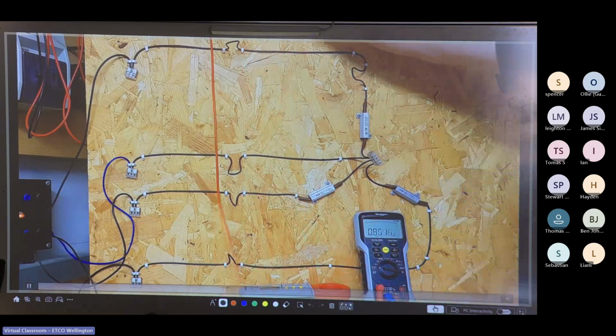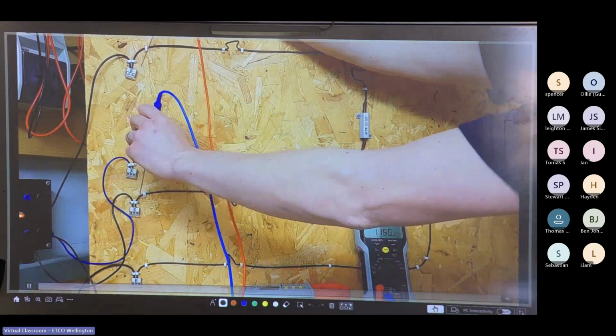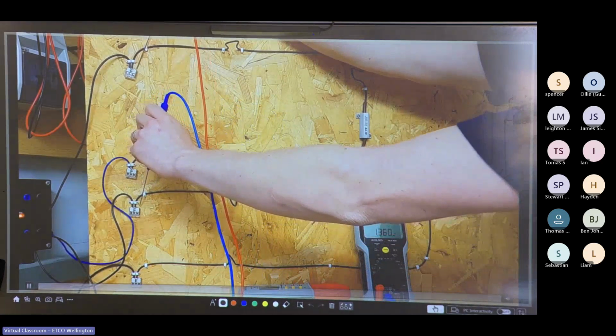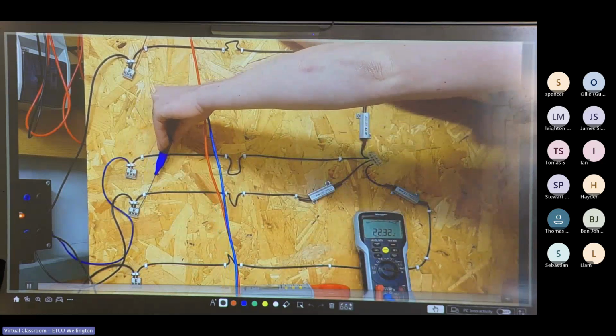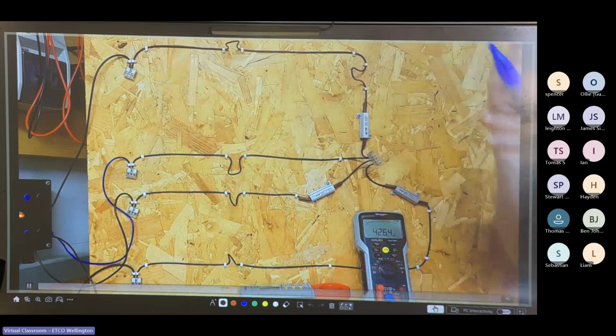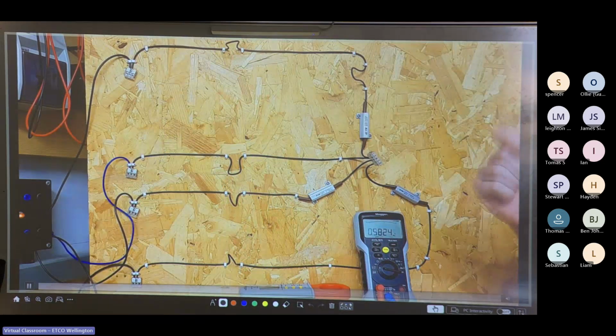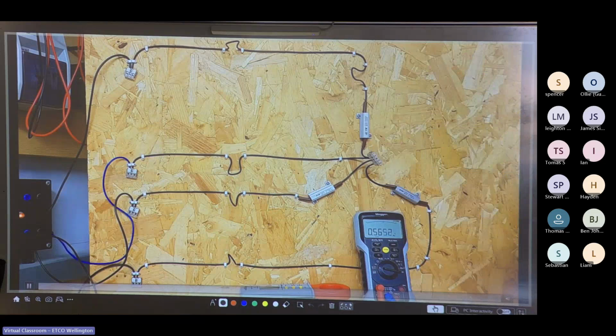Now I'm using these rather lovely Vargo connectors to make sure that I am absolutely safe there. I'm going to put these on at roughly the same time, so I don't have a live end waggling around. And then you can see that the voltage that we're measuring here is 426.3 volts. So that is our line voltage for this system that we've got connected up.